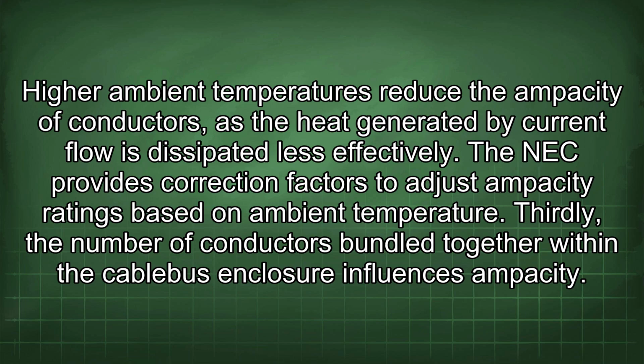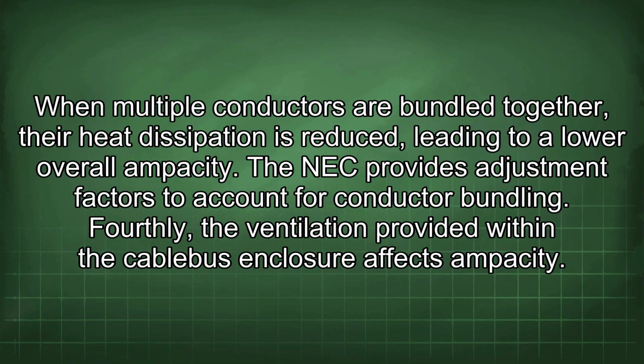Thirdly, the number of conductors bundled together within the cablebus enclosure influences ampacity. When multiple conductors are bundled together, their heat dissipation is reduced, leading to a lower overall ampacity. The NEC provides adjustment factors to account for conductor bundling.